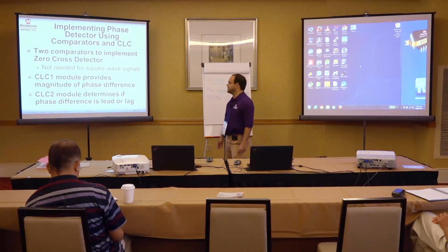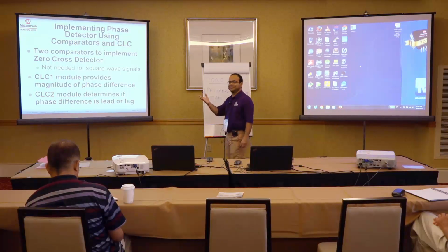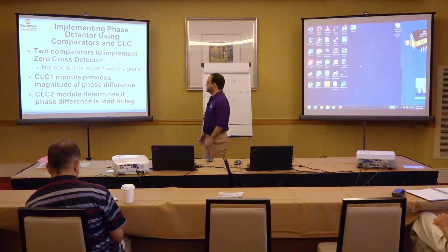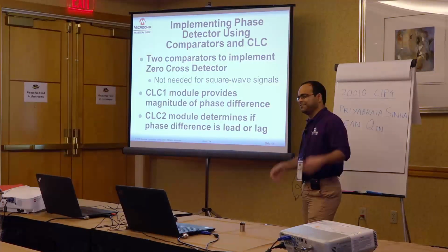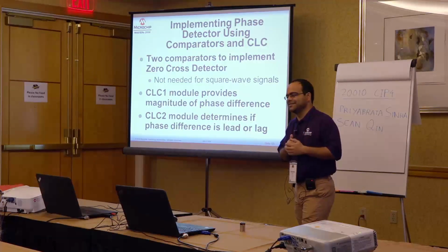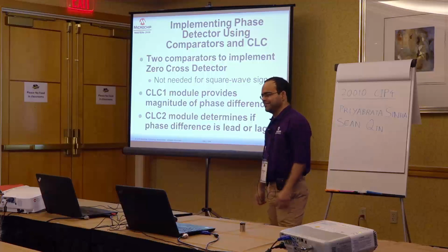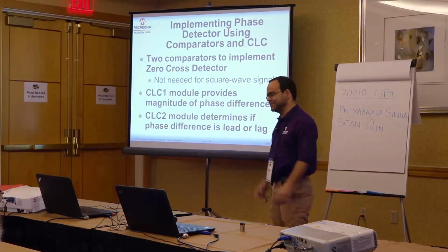So, here is another application that combines comparators along with the CLC module which you saw earlier. You may have seen this application if you attended the CIP1 class as well, but we will go over that here too. So, here we are trying to detect the phase difference between two input signals, which is useful in many applications, whether it is power supplies or distance measurement and so on, power factor correction.